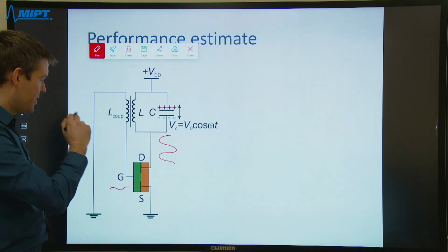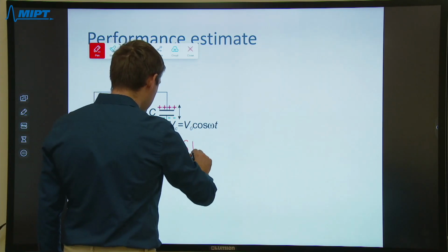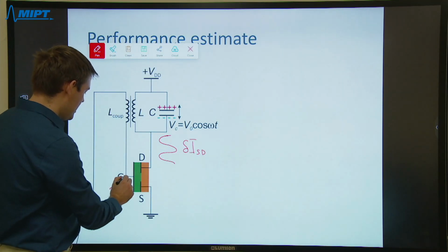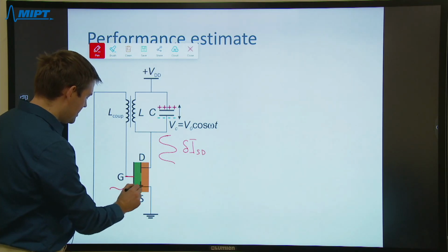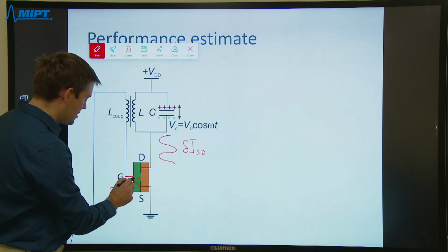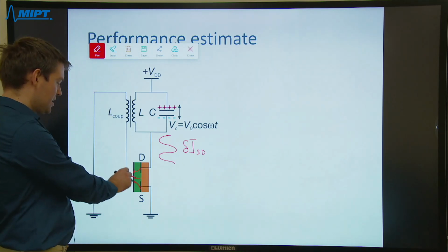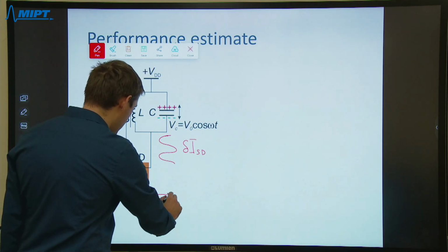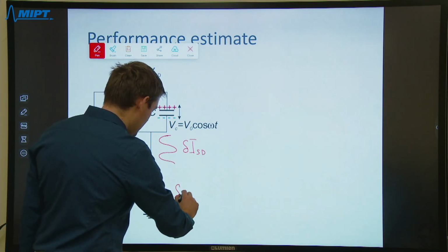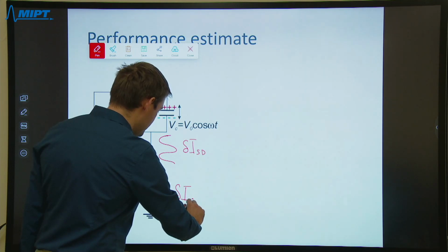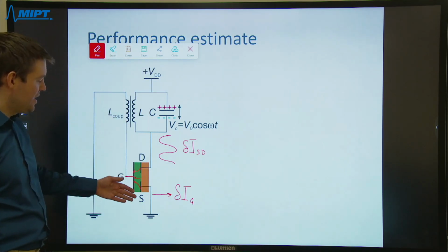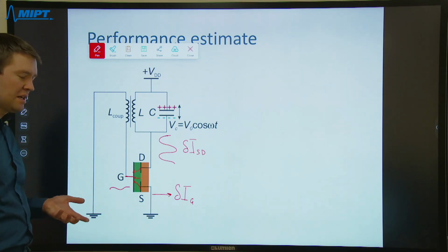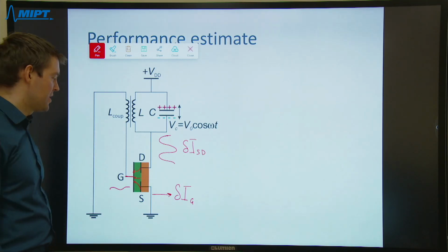Actually, it is based on the comparison of the useful current in the source drain circuit and useless current that is flowing between channel and the gate. This current can flow only at high frequencies, because only at finite frequency the insulators allow displacement current. The capacitors become conductive when it deals with high frequencies.